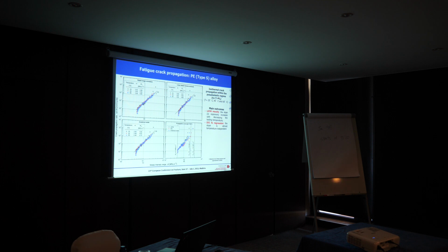Just to conclude, this figure reports the fatigue crack propagation curve of pseudoelastic material, and in particular the effects of temperature. Also in this case, by using linear elastic fracture mechanics, we see three different behaviors at the temperatures 25, 45, 60, and 85 degrees. But if we compare the results by the DIC, they become the same results.